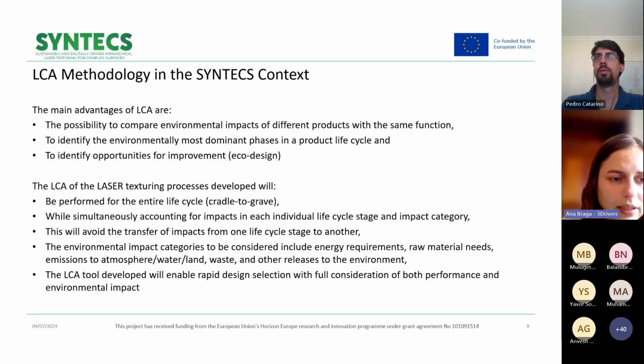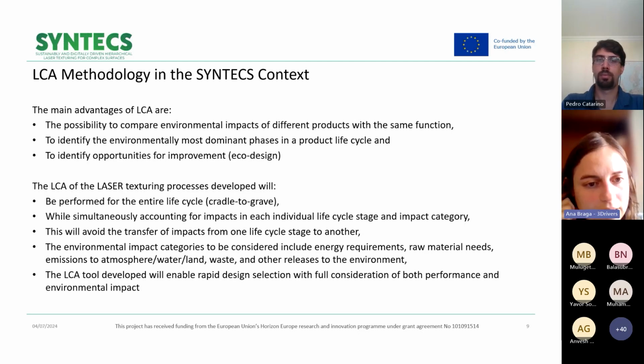And well, the life cycle assessment of the laser texturing process to be developed will be performed for the entire life cycle, so cradle to grave perspective, while simultaneously accounting for impacts in each individual life cycle stage and impact category. That is, we can identify which stage of the product life cycle is contributing most to impacts, and identify which impact it is, whether it is the global warming potential or the human toxicity.